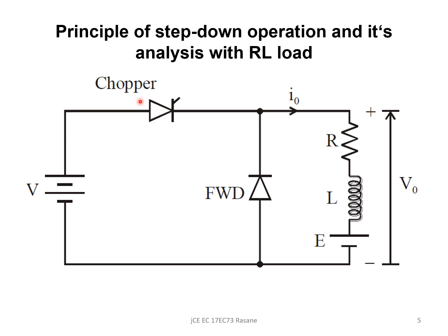And also I naught is the current that will be flowing through the load when the chopper is off. But because the chopper is off, current cannot flow here. The current will be through this diode, the freewheeling diode, which comes into action whenever the chopper turns off. The inductive energy that is stored will get a path through the freewheeling diode because it gets forward biased and the current continues to flow.